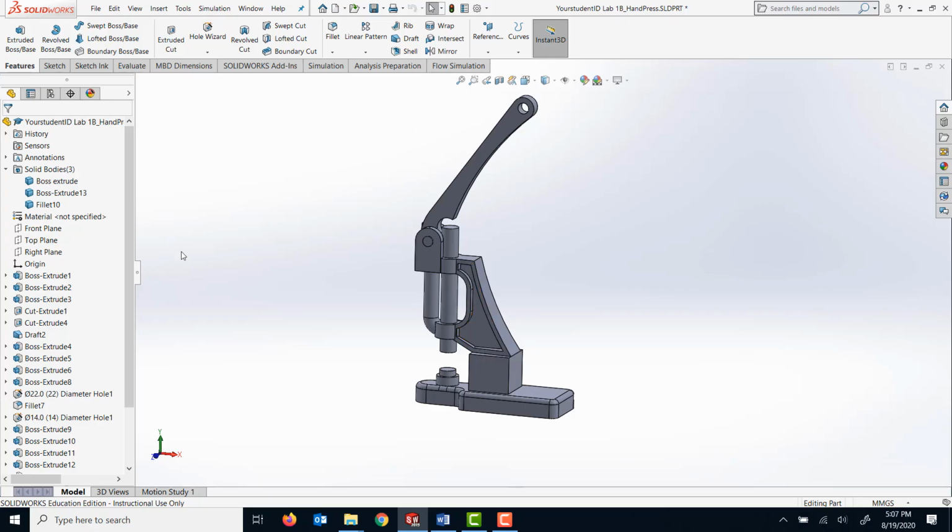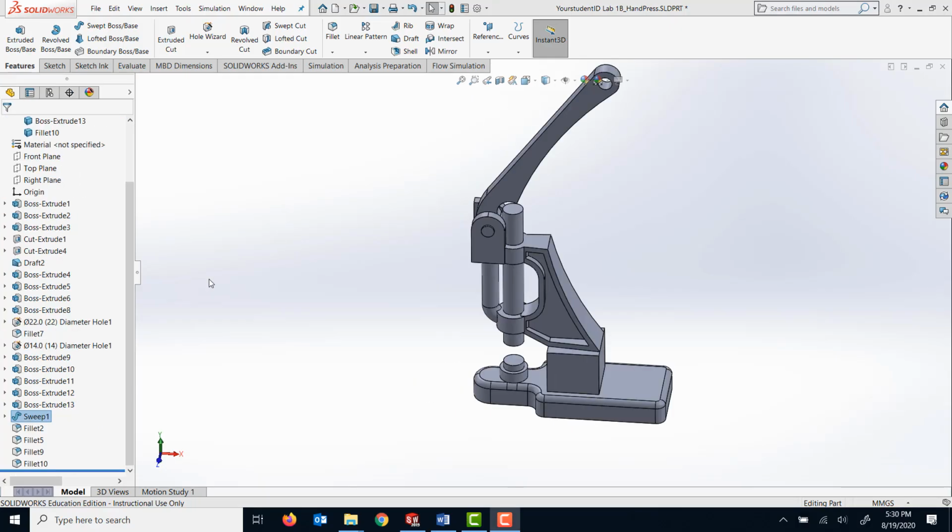It all depends on one selection. So I'm gonna show you how to create the 4 bodies from here. If you already have 4 bodies and your sweep feature did not merge together with this rod, you're fine. So you can skip a couple of first steps in the lab manual.